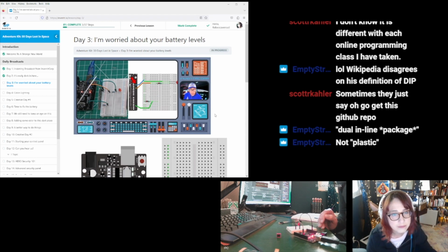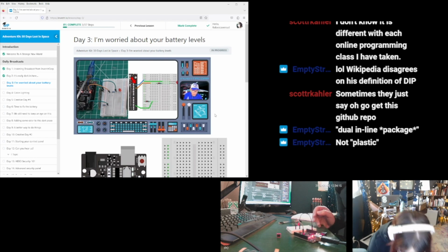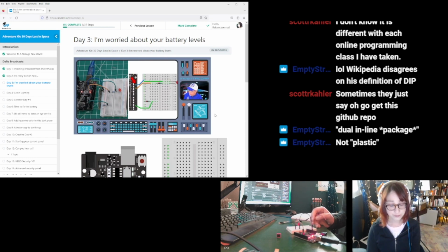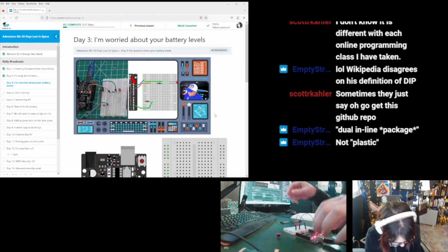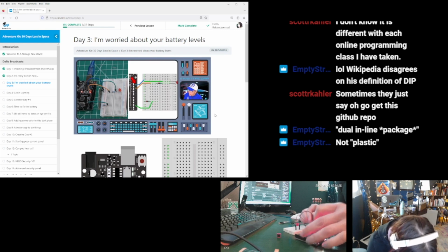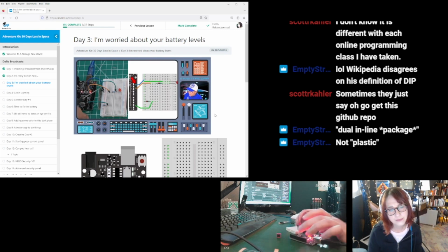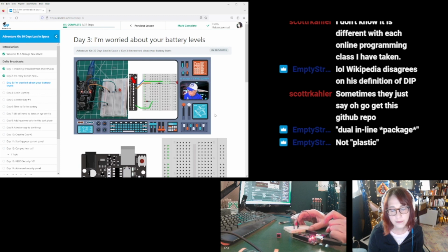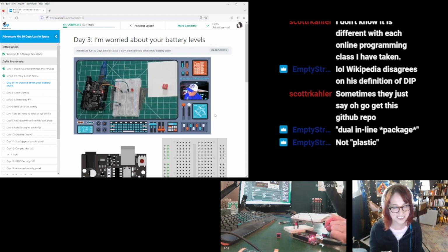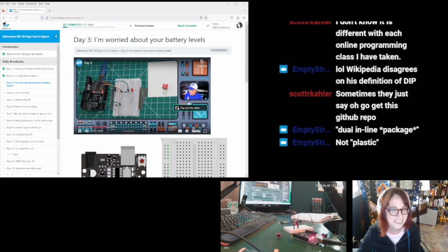And we certainly could have done that, but we were anticipating that we're going to need to build another circuit in a little while that will also want to have 0 volts access or ground. And so we've chosen to make this entire blue column right here 0 volts by connecting it to ground on the Hero. And then anytime we want to get 0 volts, we can connect anywhere on that blue column. So far, that looks like a pretty familiar analog circuit to us.